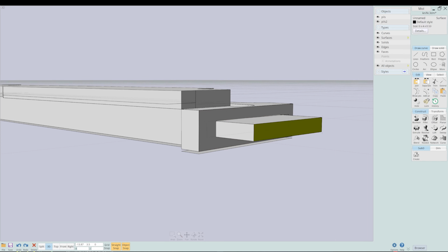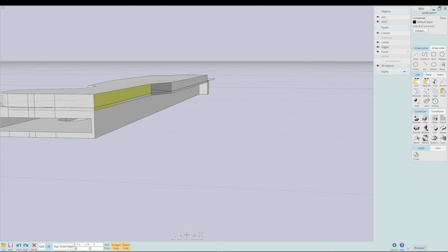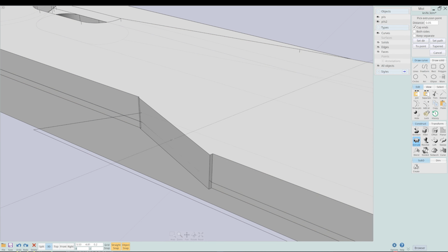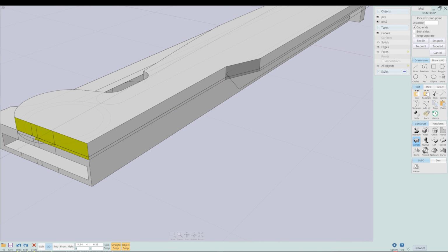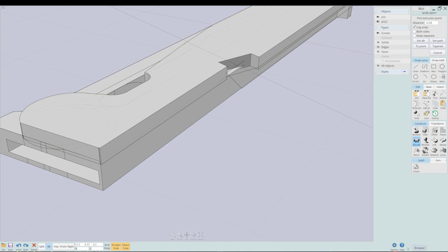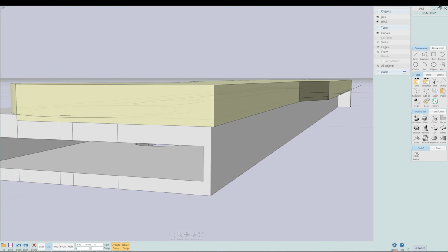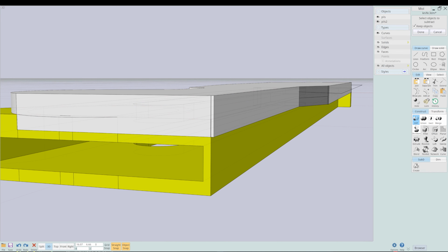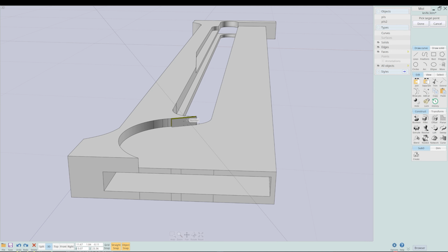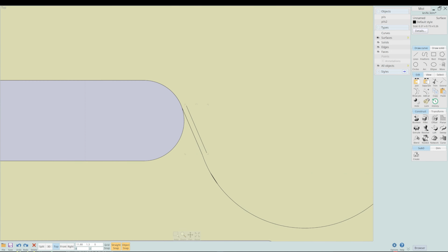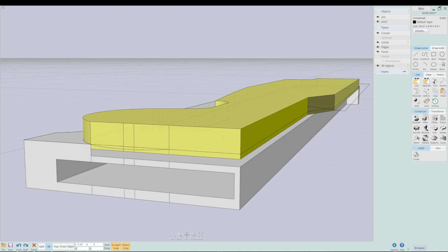And so CAD software does lend itself towards thinking about the functionality a bit more than a lot of times in ZBrush. It's just about the flow of your shapes. So what I'm doing here is I have to... MOI sometimes doesn't accept bevels or indents if the lines are completely overlapping, and so that edge was matching on the shape twice, so I had to extrude it off a little bit to use this subtractive piece.